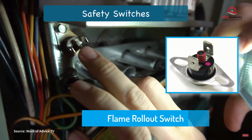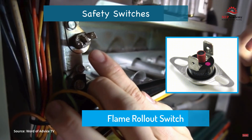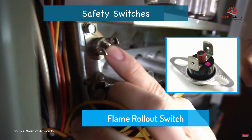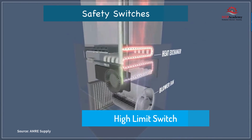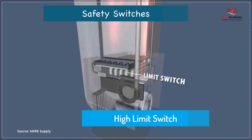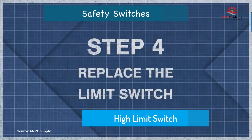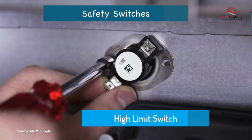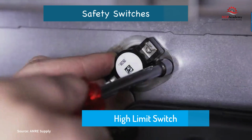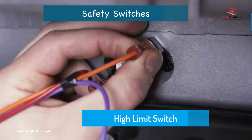A rollout switch senses if the burner flame is rolling backwards out of the heat exchanger. The rollout switch senses the flame and shuts off the flow of gas to prevent a fire. A high temperature limit switch prevents excess temperatures from occurring. Excess temperatures are an indication that something might have failed or malfunctioned. The high limit switch will shut off the gas if the discharge air temperature exceeds the limit. The high limit switch will have to be manually or automatically reset. If automatic, then the gas valve will be reopened when the temperature drops below the limit.